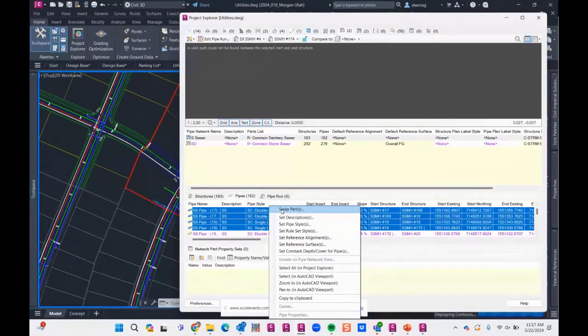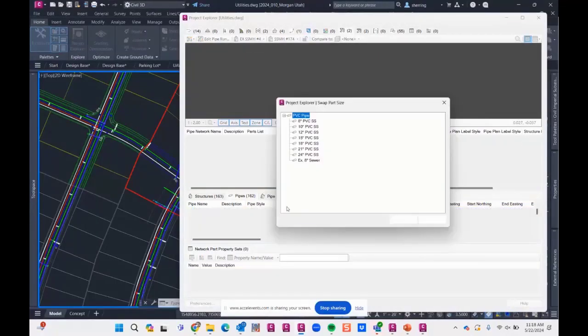Can I ask a quick question? Oh, we got time. So the feature line, when it showed the profile, did it have to be attached to an alignment for that to work? Nope. Oh, that's nice. Nope. And you can compare it to surfaces. You can see cut and fill along a feature line every 5 feet, 1 foot, 20, whatever you tell it.